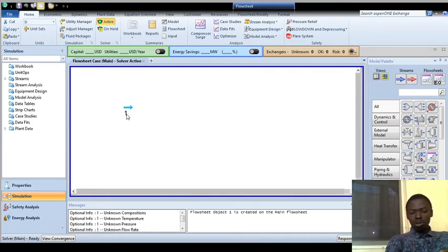You can see the temperature is what? Empty, the pressure is empty, the molar flow is empty. Now the question is, why is it bringing just these three? Aspen has been designed in such a way that once you specify these three, and your composition of course, then you can fully specify a material stream. So you can liken it to the degrees of freedom in specifying a material stream.